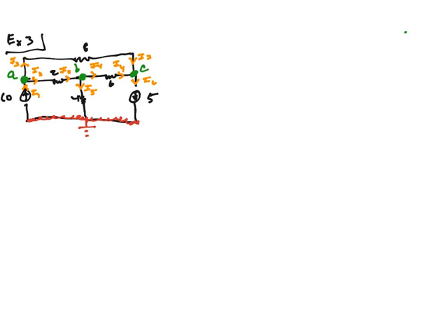All right, so again, for every node, all the wires coming out of the node are going to have a current. Some are coming in, some are going out. You choose the direction. Of course, if the current source is on that branch, then you know the direction. But if you don't, you just choose one. So that's done. Now, last step, write down my KCL equations for each node. All right, so let's do it.